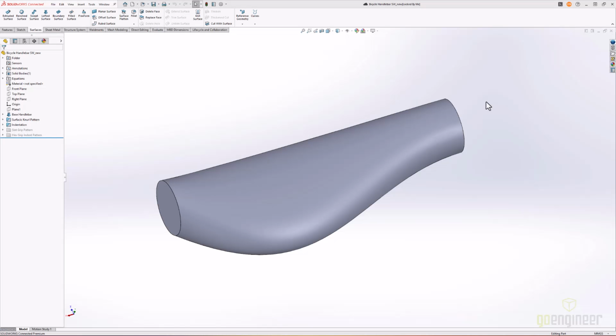Let's talk about advanced design. If you've taken our SOLIDWORKS Advanced Parts class, you'll recall that we cover a variety of topics like lofts, sweeps, and boundary bosses. Instead of thinking about particular tools, I like to think about advanced design in the context of our resulting geometry. Advanced geometry substantially utilizes non-planar, non-cylindrical, and non-conical surfaces. Those geometries are the biggest advantages all those lofts, sweeps, and boundary bosses give us.